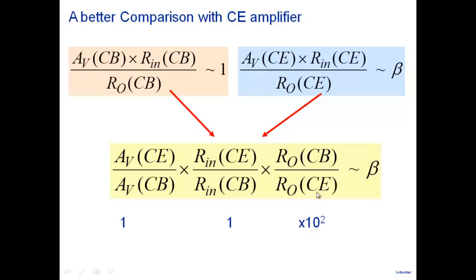So there are multiple ways in which you can look upon the two amplifiers. You can say, well, common base amplifier gives me a very low input resistance here. That's the problem. You could also say, common base amplifier gives me a higher output impedance. You can also say that, because for comparable values of gain and input resistance, common base amplifier gives you a higher value of R0.